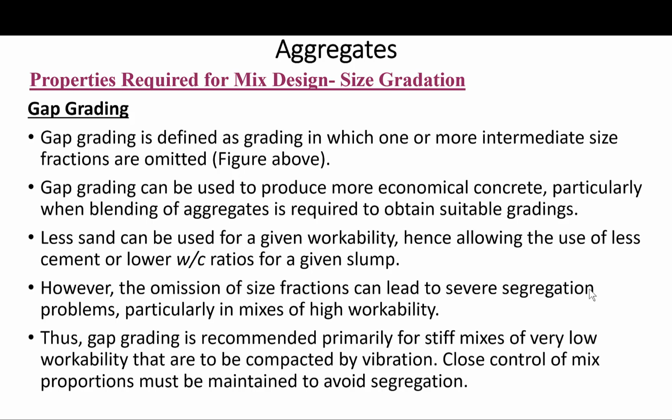And again, the finer the aggregate, the less resistance to abrasion. So the reason, as I said, is that the material often referred to as fines results in a very high water demand due to its high surface area, and because it takes the place of cement particles on the upper surface of concrete, reducing abrasion resistance. So in natural aggregates, fines are likely to be rich in clayey matter, which may increase the volume instability of the concrete. So again, ASTM does not impose limits. However, certain precautions need to be taken, okay?